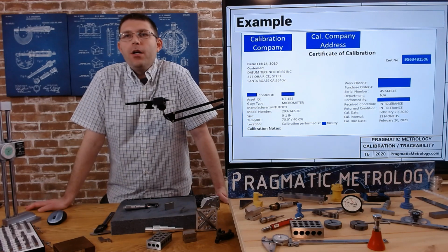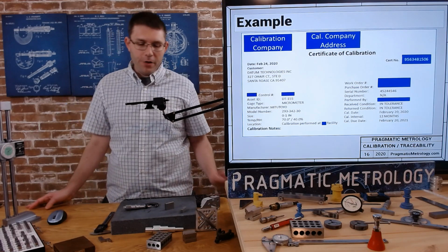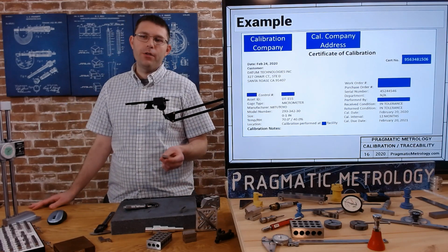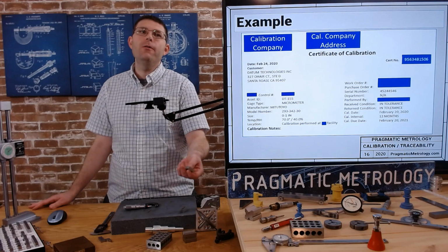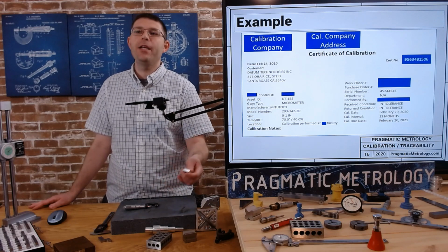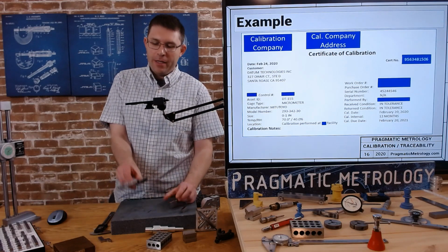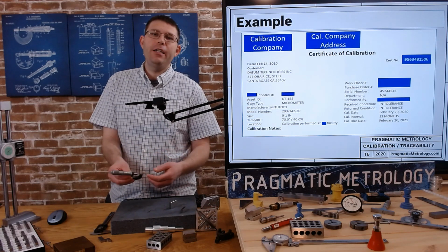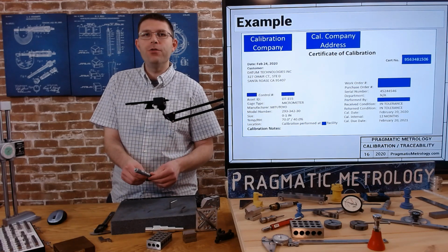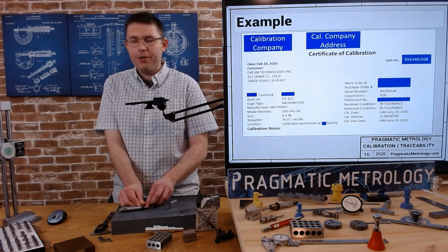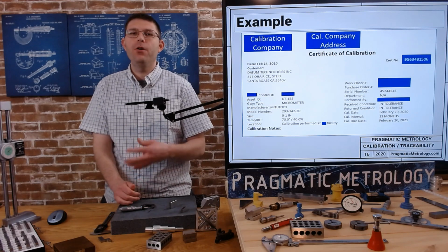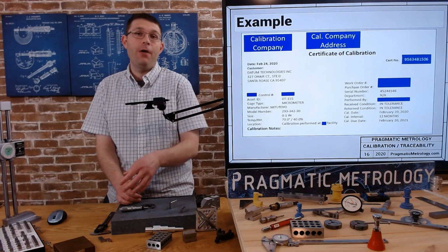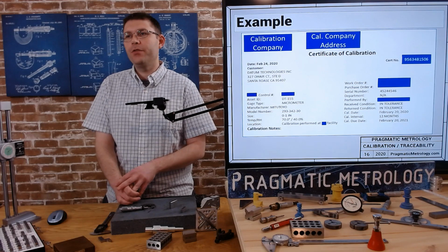So if you want to do it in-house, you've got to get your calibration block sent out. So sooner or later, you're sending something out. Datum Technologies is sending out their micrometer and checking it in-house before they use it, so that they're not having to wait a year to find out it went bad. They're finding out right before they use it if something went bad.